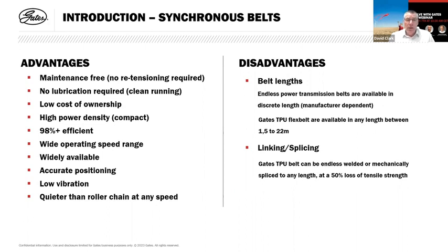Again, you have a highly engineered pulley or sprocket, and the belt tooth that meshes with that sprocket groove is meshing with a rolling action to minimize vibration as it enters and exits the pulley groove. And if you compare a belt to a roller chain, you'll find that a belt is generally quieter than a chain at any speed. It's not all advantages for belt drives, of course.